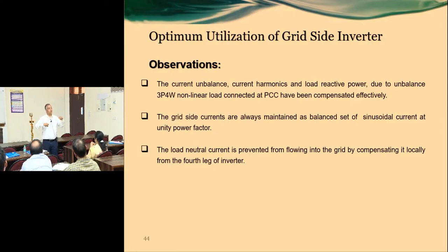If it is going to be more, if all such devices are going to behave in that way, then definitely some energy storage devices are there, but they will only exchange the active power. Reactive power and harmonics you have controlled at the generation itself, at the generating end itself. So exchange of active power can be managed. But for reactive power, you have to install a capacitor bank or reactor. That can be avoided. The crux is that.